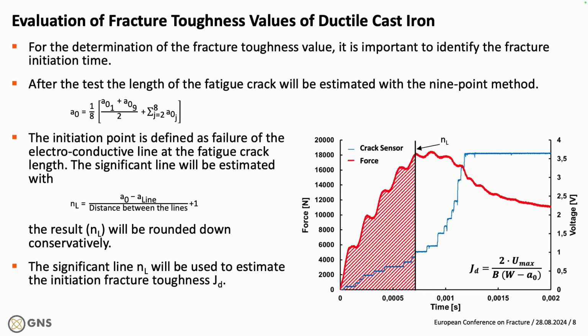So for this, we made a procedure to correlate this crack line with the fatigue crack, and with this we can find out at which time the fracture initiation took place. After that, we can evaluate the fracture toughness of this specimen.